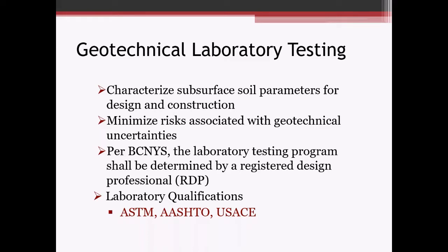However, subsurface soils are highly variable, depending on the mode of deposition by Mother Nature. So to help minimize those risks, lab testing is performed on representative samples in accordance with established test procedures, typically published procedures by the American Society for Testing and Materials, or ASTM, for roadway projects.